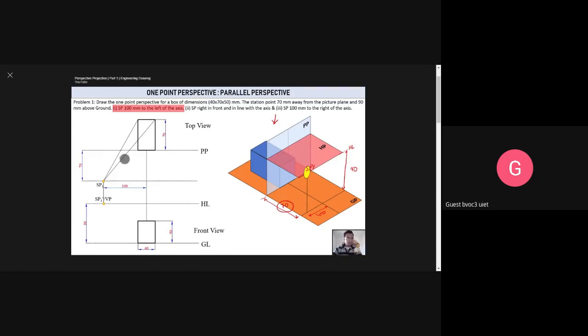Now, top view done. We are watching it from here. Okay, this is the top view, and for making the corresponding front view, how would it appear in perspective? What you need to do is watch this. All the points 1, 2, 3, 4, all the points have to be connected with this vanishing point. Okay, and before that, you need to bring all of these points over here.